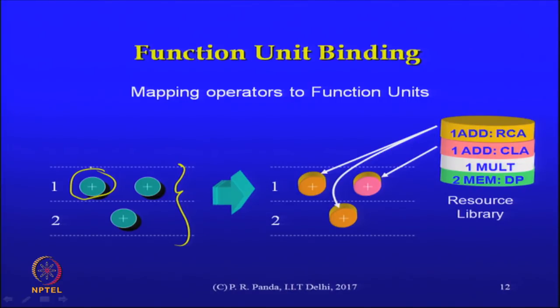What it looks like we will get to later on, but informally, a node represents an operation, and the edges, which I did not draw here, represent dependency structures. That is important information for the scheduler, because the scheduler needs to take these dependencies into account before deciding which one should go into which clock cycle.